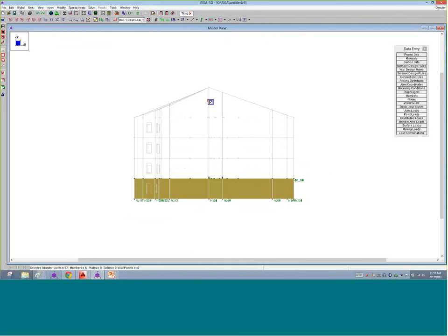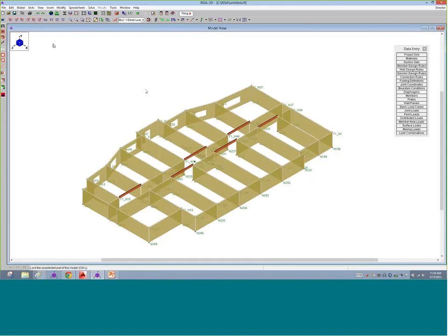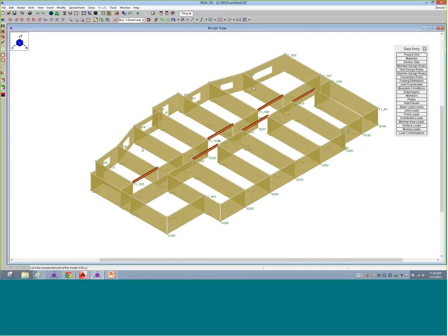And I can lock out my view of that top structure using this lock button. Once I lock that out, I can look at this in isometric view, and I get to see the entire structure on my screen. This is so much easier now. I can do that floor by floor, pop from floor to floor to floor, seeing what's happening in the structure and verifying on each level. Otherwise, it can get a little complicated.